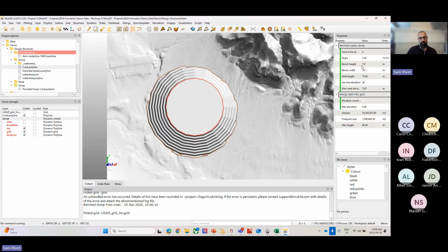Okay, so once again, it goal seeked a bench height of 7.9 meters from 5 meters to achieve that reduction in footprint area. So, I have a fairly intricate structure, not overly complex, but still a lot of benching here. And I just goal seek 2 different parameters fairly quickly to achieve a design that I want.